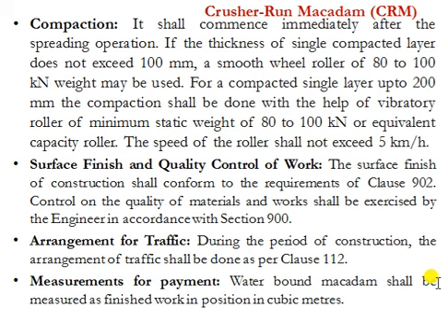So here also the compaction is done in the same way as in the previous method, that is wet mix macadam. If the thickness of a single compacted layer is less than 100 mm, a roller of weight 80 to 100 kN is used for the compaction.